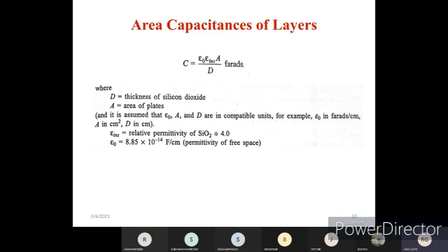If you remember, we have taken a P-type substrate, and on the P-type substrate, first we deposited polysilicon. After that we go for the photolithography process, after which we etched some portion of the substrate so that I can deposit N plus material for the source and N plus material for the drain.